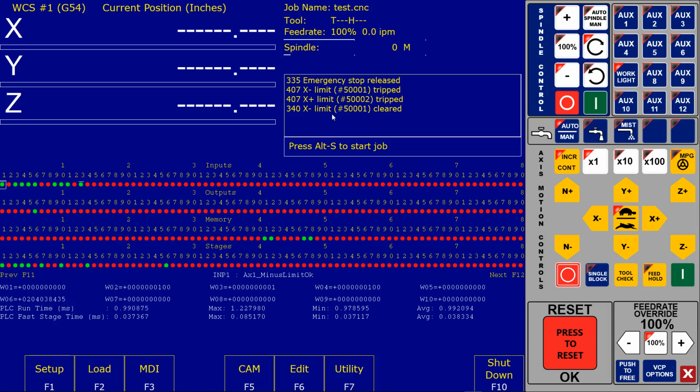And it definitely makes it a lot harder when support is trying to troubleshoot something, because if you invert inputs 1 through 6, and then all of a sudden you call up saying that the axis isn't moving, Centroid support is probably going to start going through the typical standard things. All right, do you have motor voltage? Do you have power going to the drive? Are you getting any kind of faults? And how I found this out was that I actually TeamViewered into someone's system, and when I brought up the PLC diagnostic, I saw that they inverted all their inputs.